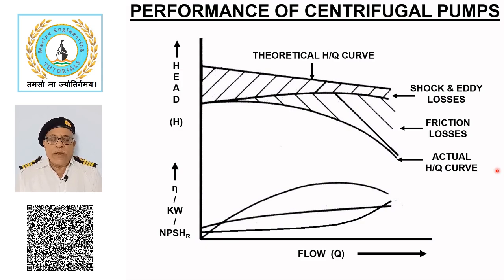It provides important information for the pumping system designer and operating personnel. Reason for low rate of discharge by a centrifugal pump is due to large head requirement caused by a restricted line, very long discharge pipe, high viscosity of the liquid or discharging to a high level.